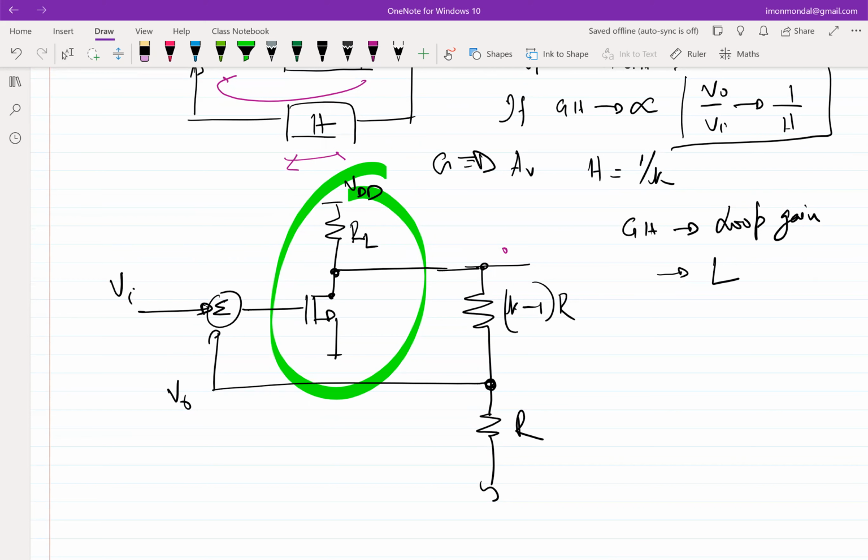Okay, fine. So this is negative. And by the way, in order to check this, you need not always inject the error at this node. You can inject it anywhere in the loop. You can start off here. Let's say this increases, this increases, this increases. So it comes back and this decreases. Right? Anywhere in the loop. That's the good thing about a negative feedback loop. You can do this analysis, I mean, hypothetical analysis, by injecting error anywhere in the loop. It's a property of the loop, so it doesn't change where you disturb it. You don't even need an input in order to figure out how the loop behaves.